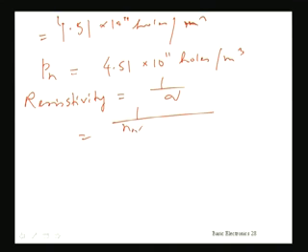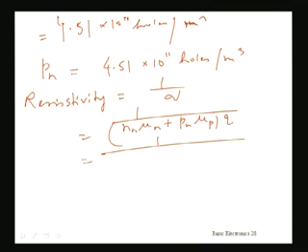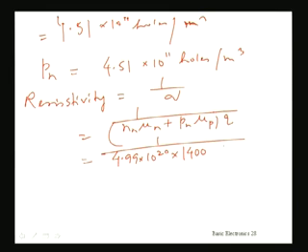Sigma is equal to Nn mu n plus Pn mu p, into Q. So, it will be equal to, here Nn electron concentration is 4.99 into 10 to the power 20 into mobility of electron, which was 1400 cm square per volt second. So, I will be converting everything to meter unit. So, I will have to multiply 10 to the power minus 4 with 1400 plus